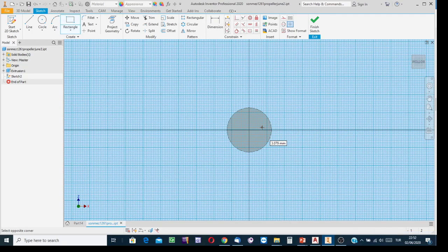Okay, arbitrarily create a rectangle. In my mind, this strip corresponds to the edge of the propeller, the blade of the propeller. Well, to be able to input the dimensional constraints, have the characteristic point of this boundary, applying the project geometry process.